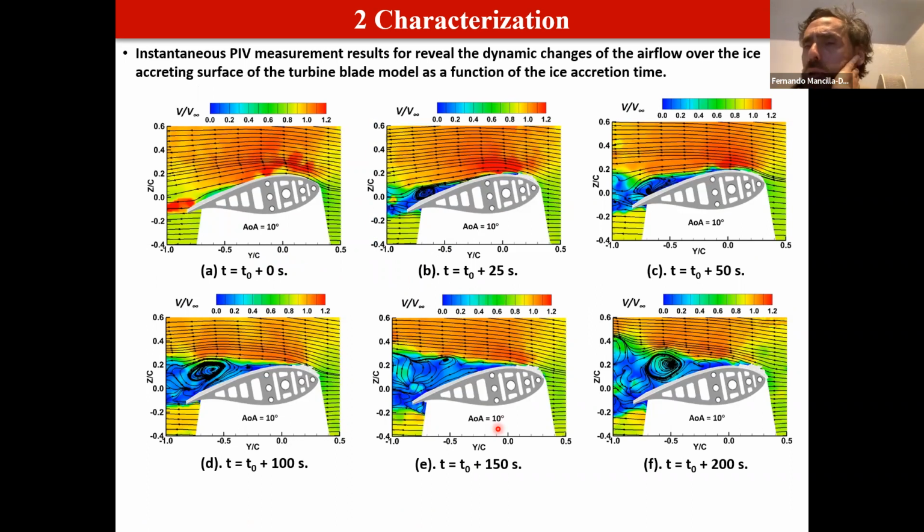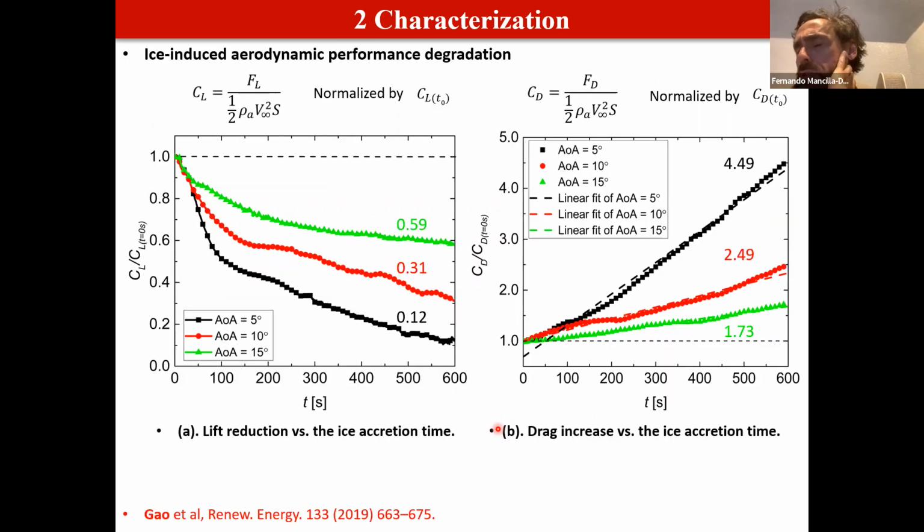You're mentioning that to avoid this degradation, you might use pitch control, but that pitch control is also used for maximum power point tracking and things like that. So the idea is to use the same actuation, but just with a different control objective. Is that more or less what you're referring to? Yeah. So for the wind turbine pitch control, we can set a small bias value to the current pitch control algorithm under different conditions, and we can adjust the value of the bias to get the optimal power output under different icing conditions. I see. Yeah, perfect.